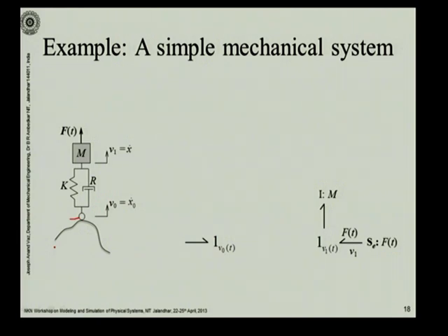So there is going to be a rate of change of this motion, okay. So here you are having a velocity, and that is being imposed by a source. It's a source of flow. Here on this side you have a source of effort, here you have a source of flow, okay. And across these two ends you have the spring and the damper.